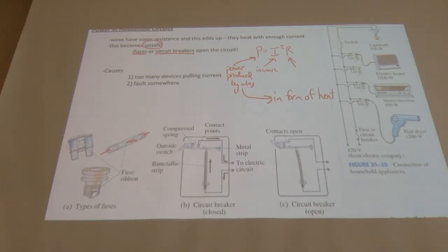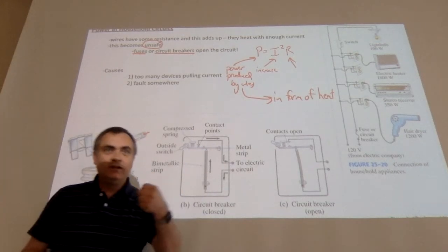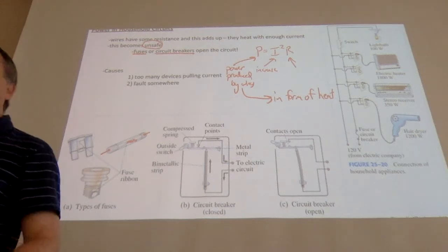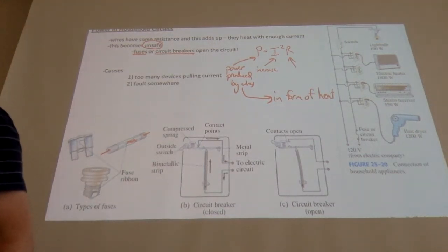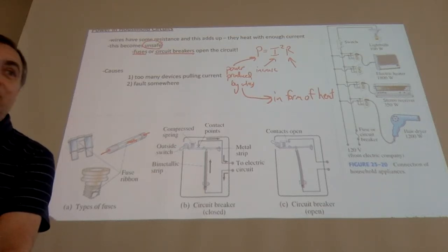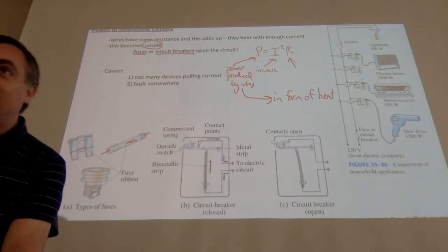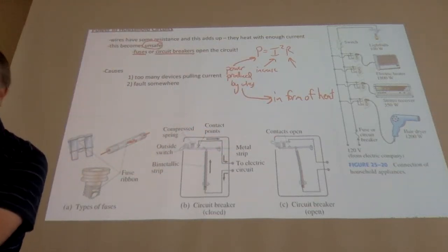You look at the little devices behind the little gray door, and they have numbers on them, and maybe one of them says 40. And you're like, I'm going to Home Depot, and I'm going to find one of these little things that looks exactly like this, except it says 50. Because I bet 50 is better than 40. Right? And then you put that in the thing, and everything stays on all the time until your house burns down.